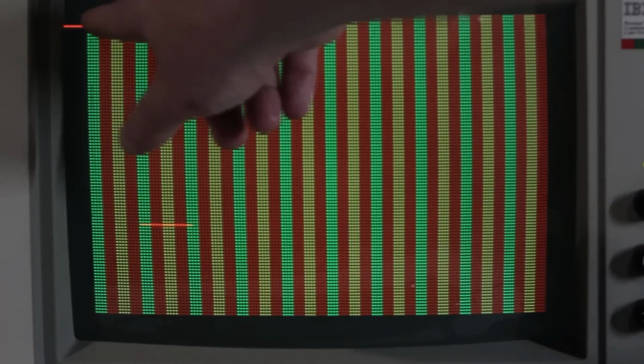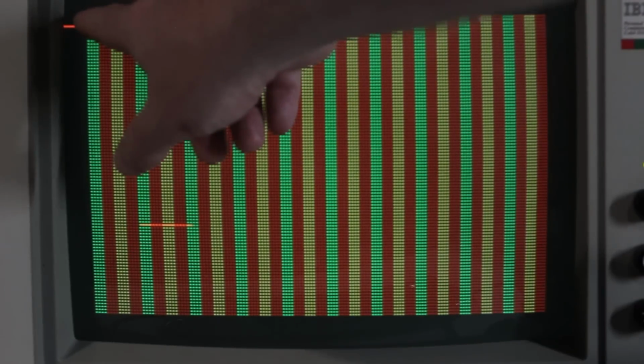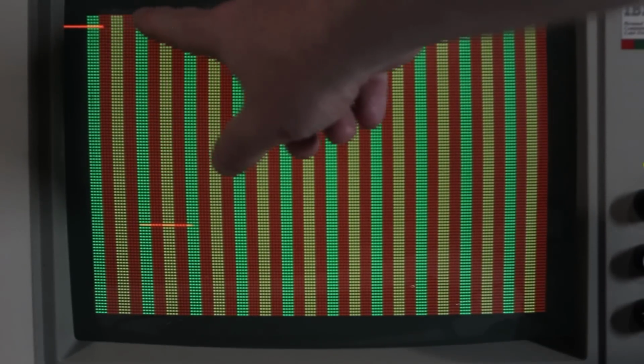Now, once that happens, I know I'm in one of these 16 H dots, but how do I get control down to the H dot precisely? Well, the CPU is running 3 times slower than the graphics card. If you count it out, there are 16 H dots per character, there are 8 characters. This is not a multiple of 3 H dots, so it's not an exact multiple of CPU cycles.